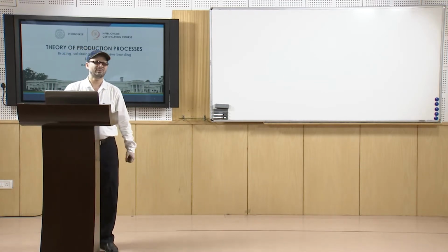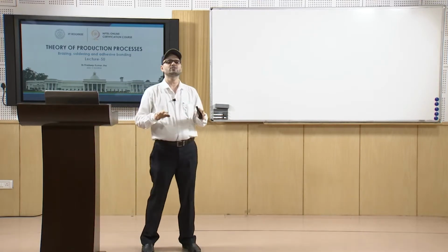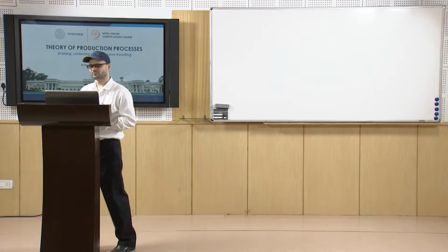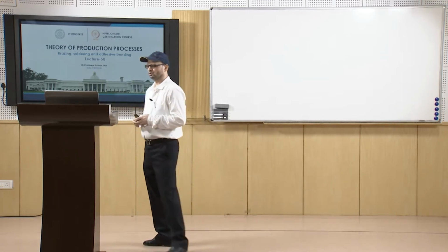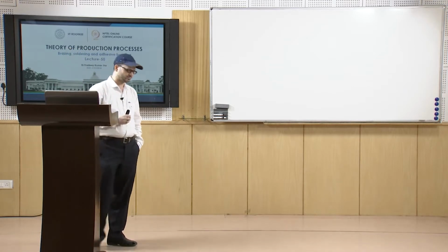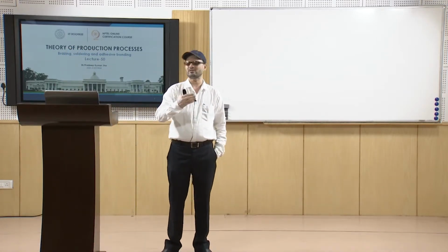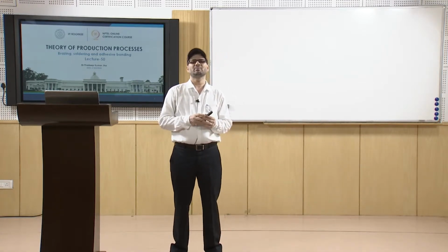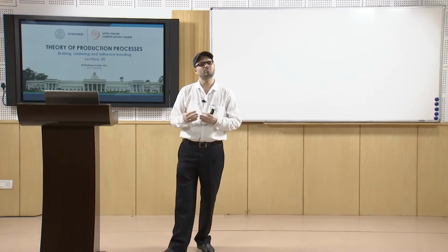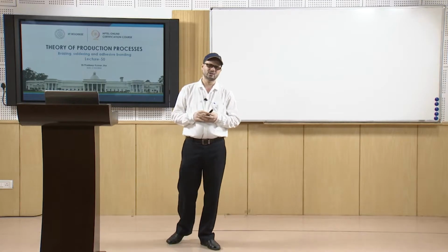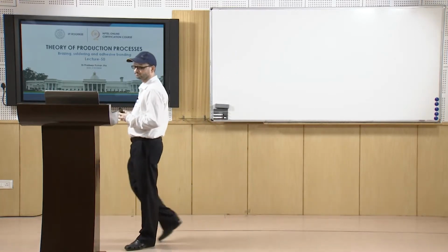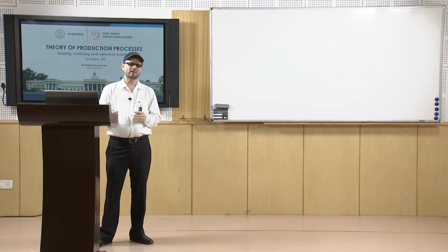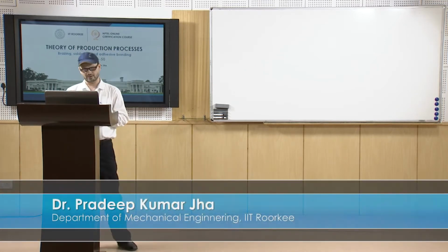There are many methods of having a proper surface finish of the material, such as sandblasting, and as we discussed, we can use brushes and chemical agents. And fluxes, many a time, are corrosive in nature. We have different types of fluxes that we will discuss. Once the process is done, you must remove these fluxes, because otherwise they will create undesirable effects. Normally you try to wipe them off, and you also wash them vigorously with hot water, so that the fluxes or their residues are removed.